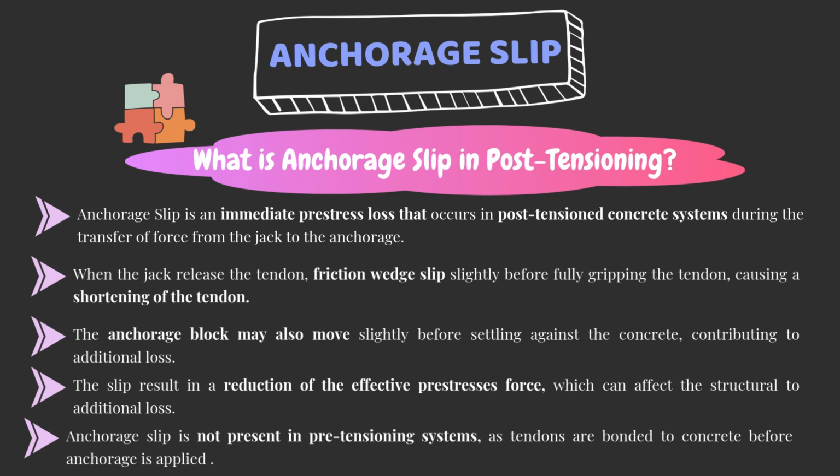The third immediate loss is anchorage slip. So what is anchorage slip? First, anchorage slip is an immediate prestress loss that occurs in post-tension concrete systems during the transfer of force from the jack to the anchorage.